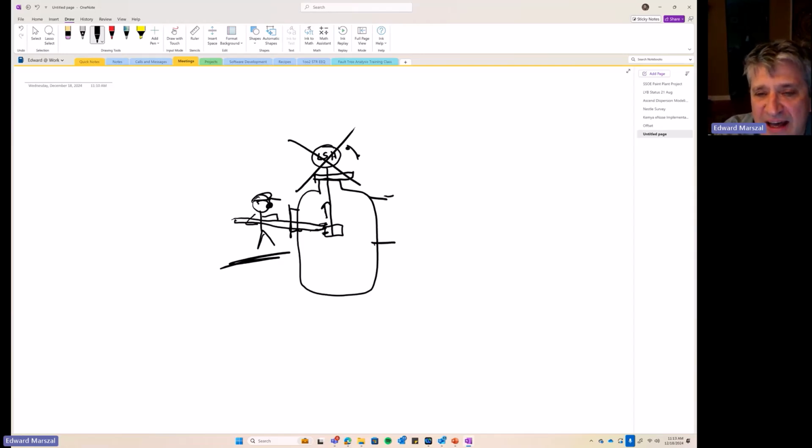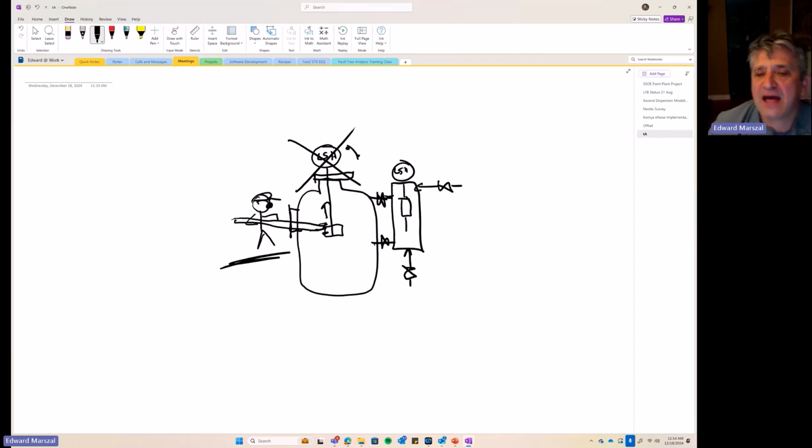You should instead have your level switch on an external bridle that you can isolate from the process, and you can fill and drain from the top and bottom. And then you can test the device in isolation of the process. And this test with an external bridle won't have the potential failure mode of somebody broke the float with the 2x4.